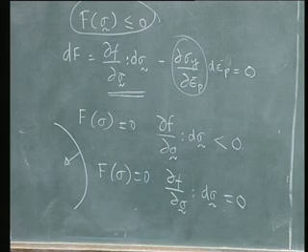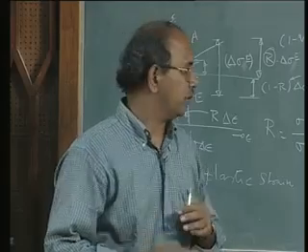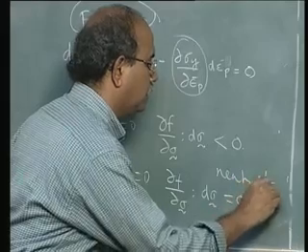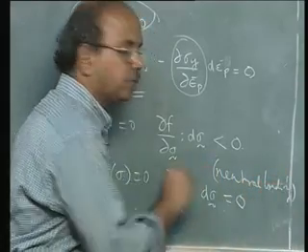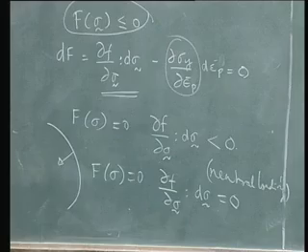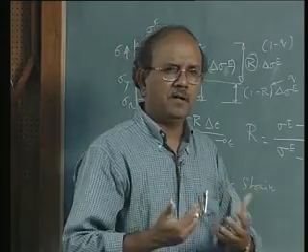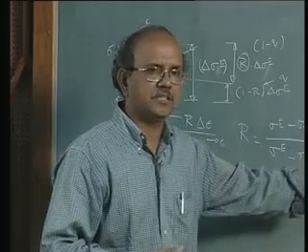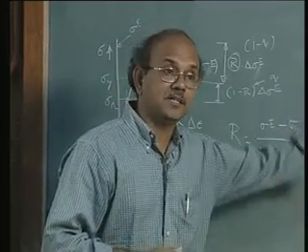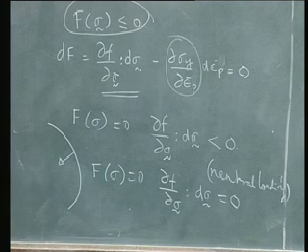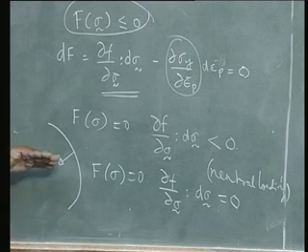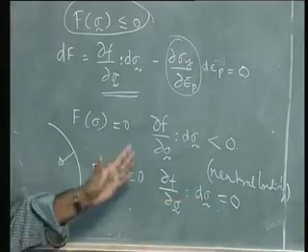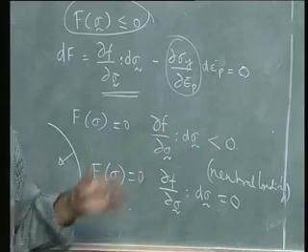Loading, or in other words called neutral loading, in the perfect plastic case. So what essentially we are doing is to pick up an analogy between the uniaxial case and the multiaxial case and trying to express conditions, because I have to calculate these conditions for my stress update also. From a plasticity point of view, it is important, no doubt, but from our point of view, in order to develop a numerical algorithm, it is important that I understand these things.